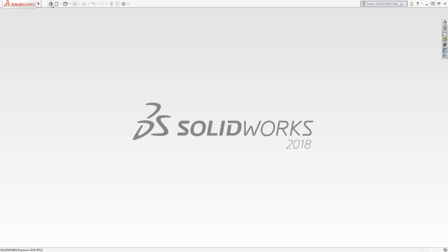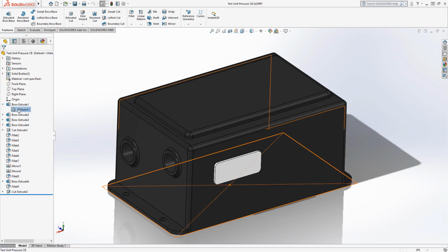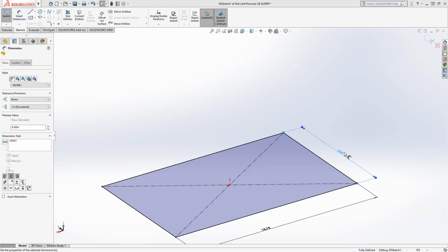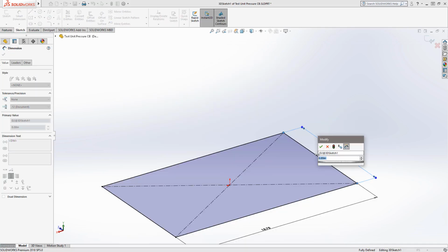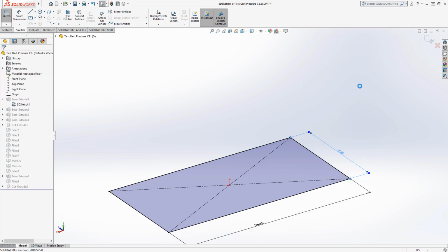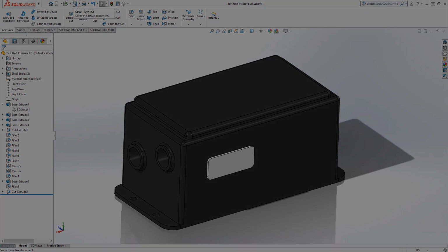This would typically mean deleting and reinserting and manually updating. But since we use AnyCAD, when we inserted the file, the only thing we need to do is make updates directly inside of SOLIDWORKS. Once inside of SOLIDWORKS, a quick change from 8 inches to 6.5 inches is made. Once the file has been saved, Inventor will recognize the need to update and prompt you.